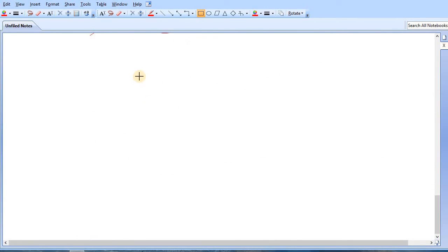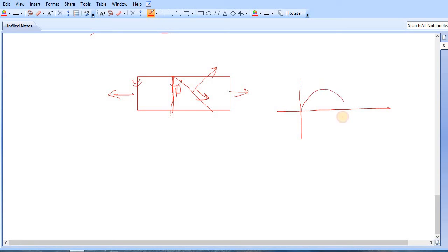Again, recap the previous cases where simply you have applied a single tensile stress, and here the plane was 5 degree away from the actual normal plane. To find the normal stresses you have used already the graphical method. So what was the case there? This was sigma x, and to find the stresses on this plane you have rotated this radius anti-clockwise for 2 phi angle. Then corresponding to this point you have found this normal stress as well as this shear stress.